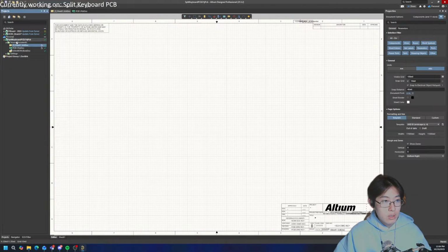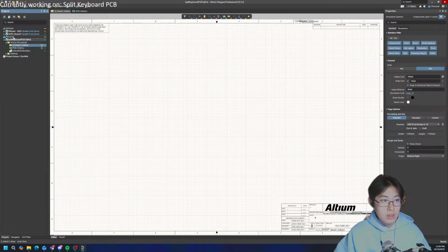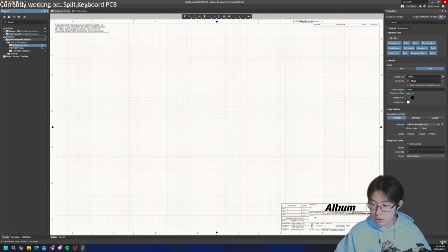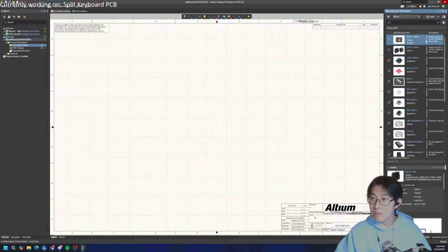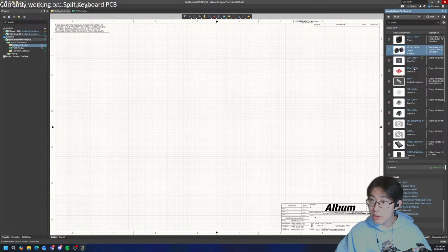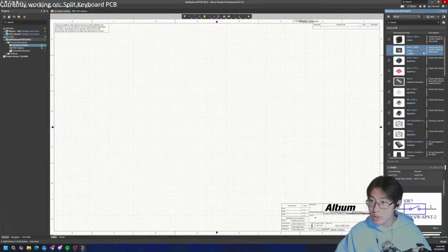What I can do though is I am going to get started by making a component library. So I think what I need to do is to create components. Switches. I wonder if there's already a switch created though. Let's see. Manufacturer part search. Cherry MX. We do. Alright. Oh, that's a really ugly 3D model. I wonder if there's a better one. The footprint is not present. So only these two have the actual footprint. Interesting.